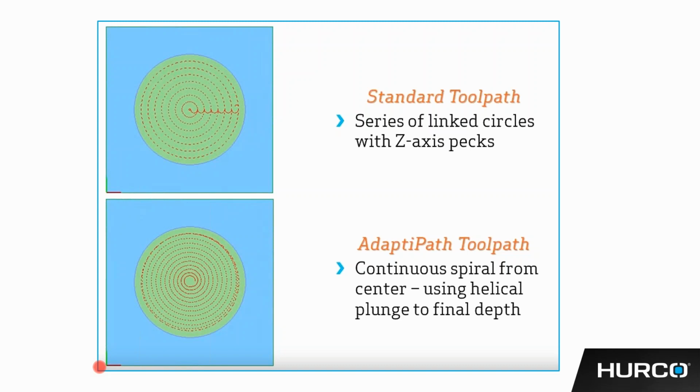And if you were to take a straight line cut along the edge of your part, you can dial in your feeds and speeds, width of cut, dial all that in, and then you can use those same parameters for your pocketing, because the control will guarantee that you will never take more than that width of cut that you specified. So the spiral works really well for this circular shape.